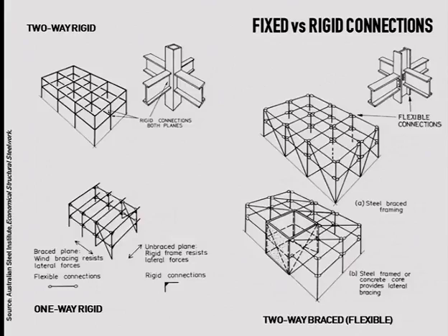And why that? Because look at this joint here. What happens in space? We've got 3 degrees of freedom in terms of translation and 3 degrees of freedom in terms of rotations. So one element, whatever object in space, is able to translate on the X, Y, and Z axis, but also able to rotate about the X, Y, and Z axis. When we weld two elements together, that's a fixed connection, it's rigid. So if it's not able to rotate, bending moment is transmitted to the next one.